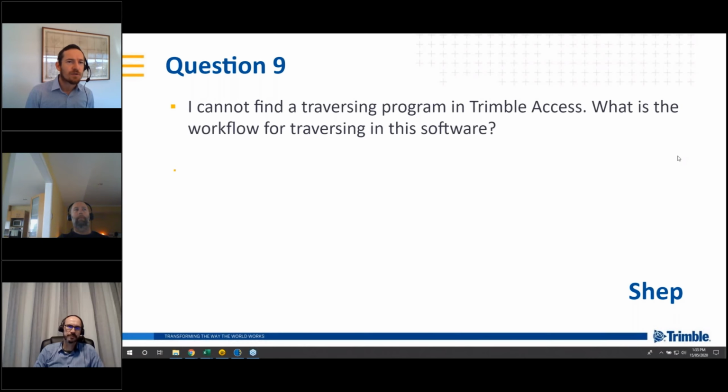If you're just doing your normal setup, backsight, foresight, and then moving on through, it will recognize that they are, I guess, contiguous or joined measurements, and you can key that traverse in. So it's just a standard routine. There's nothing different there. You can choose to measure rounds or just take the observations and keep moving on.